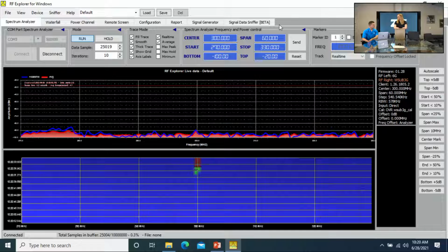That was really neat. It was still there a little bit until you kind of... Until it's fully zipped, right? All the way over, and then it dropped down. And that peak, I think, was maybe 40, 50 dB above where you had the noise floor at. So even this simple demonstration shows how a shield can have that much of an effect on a signal. Hopefully, bring it down to a range where it's not causing problems anymore, right?